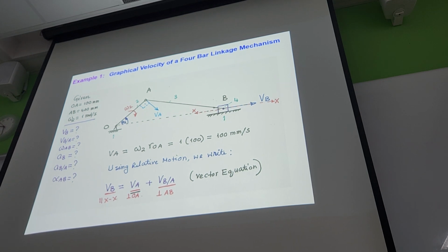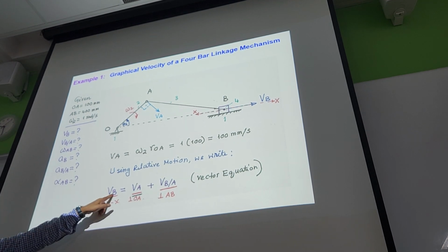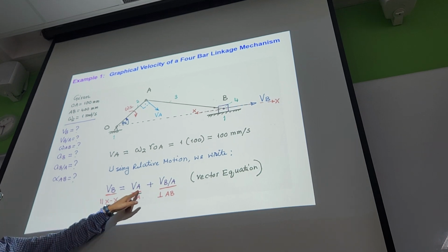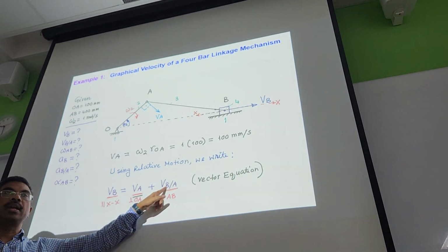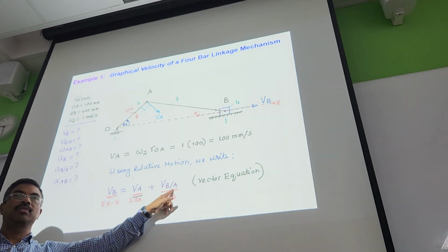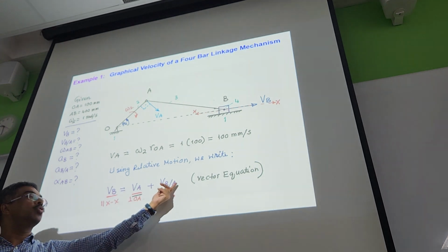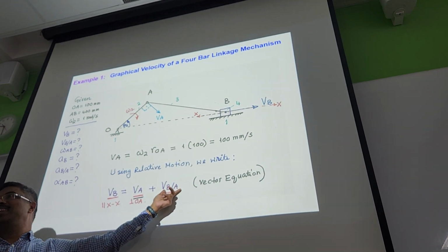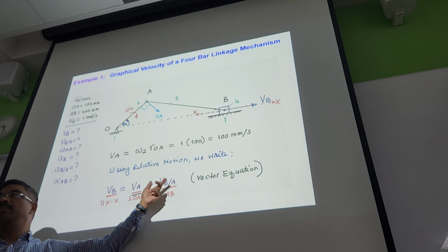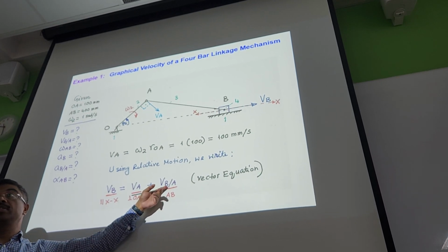And then there is another point it said. The absolute velocity and acceleration with 1 letter index, they should also start from the origin of the vector polygon. So let's see how we have 3 parameters. We have a 1 letter index of VB, we have 1 letter index of VA. This, VBA, is a 2 letter index. It is not a 1 letter index. And this one is called absolute velocity, this one also called absolute velocity. This 2 letter index we call relative velocity. Correct? Not absolute velocity, relative velocity.